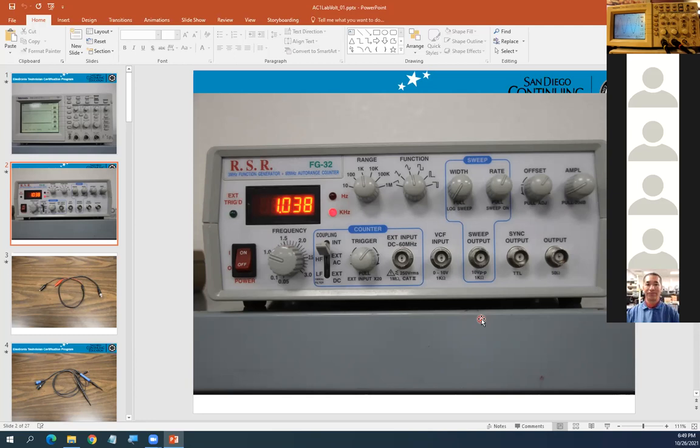Okay, as far as sweep and counter go, the counter is on EXT AC, so I guess that has to do with us doing AC. But for those two, sweep and counter, we don't worry about those knobs when we're doing experiments unless you tell us to? Yeah, you don't touch that. Okay, all right. The only time is when you're using your signal not from the generator, then you can connect to the external input. Okay.